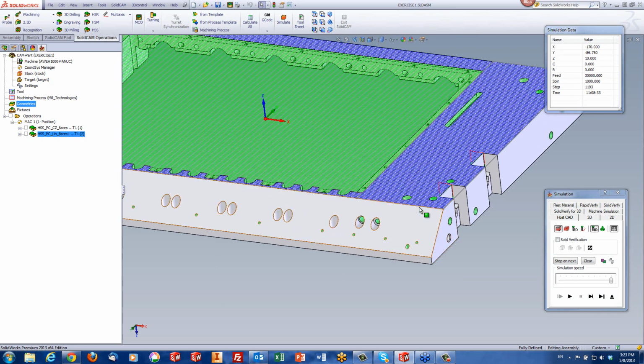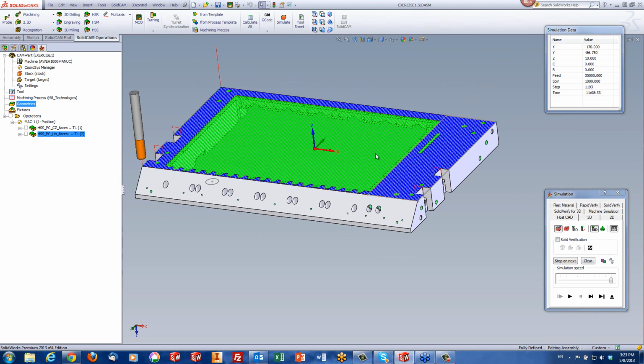Same thing over here. And for such a large area to go slowly over the cutting area, wherein you're not cutting, doesn't make sense to me. Okay? Obviously, if you actually really did have material over there, then I would say, okay, leave it and do it this way. But let's say we don't, everything was cleaned out over here. So what I'd like to do is to move rapid. Now, when it goes up to my clearance area and goes across, it moves rapid.